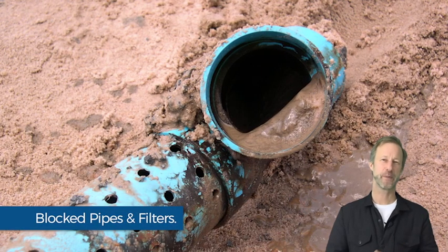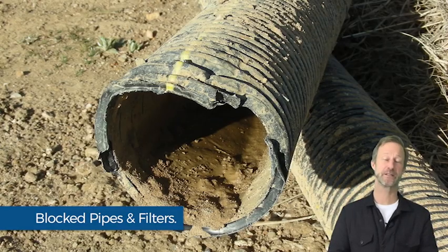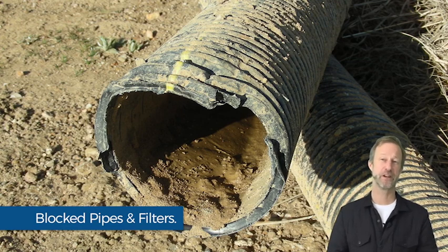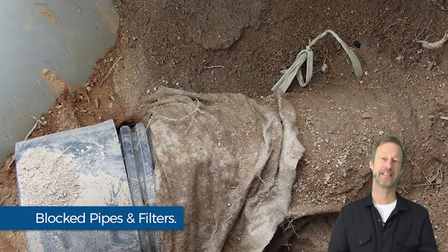The system began by simply drilling holes in the pipe. Later, ribbed, thin-walled, large diameter pipe with factory-cut slots became the standard. The migration of soil particles inside the pipe remained. Later modifications to the system included encasing the pipe in aggregate, hence the name drain rock, and pipe wrapped with geotextile filter. Well, encasing the pipe in drain rock changes the drainage assembly considerably.